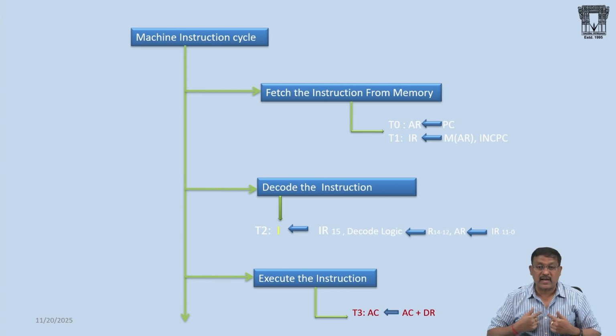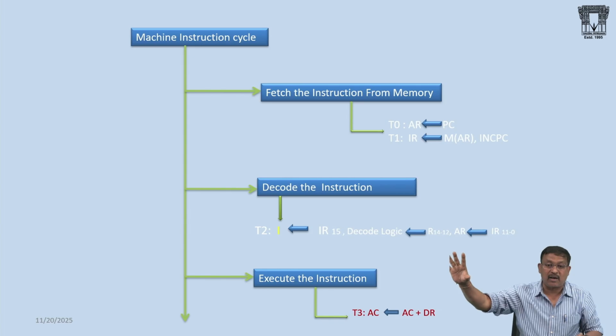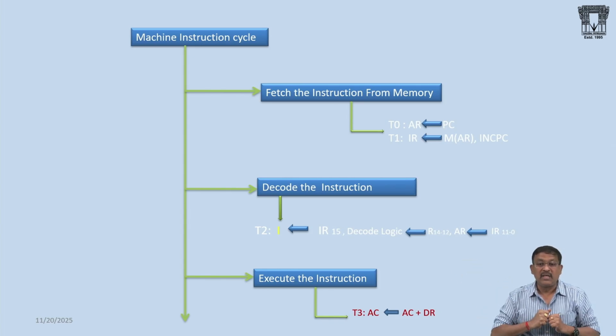If my processor is a stack related processor, I have to push the first data into the stack location, push the second data into the stack location, and perform an add operation. This is a 0 address field instruction, add. If I want to perform a subtract operation, SUB, that is a 0 address field instruction, because my processor is a stack related processor. But in our context, our processor is an accumulator organized processor. We have to obey the fundamental principle.